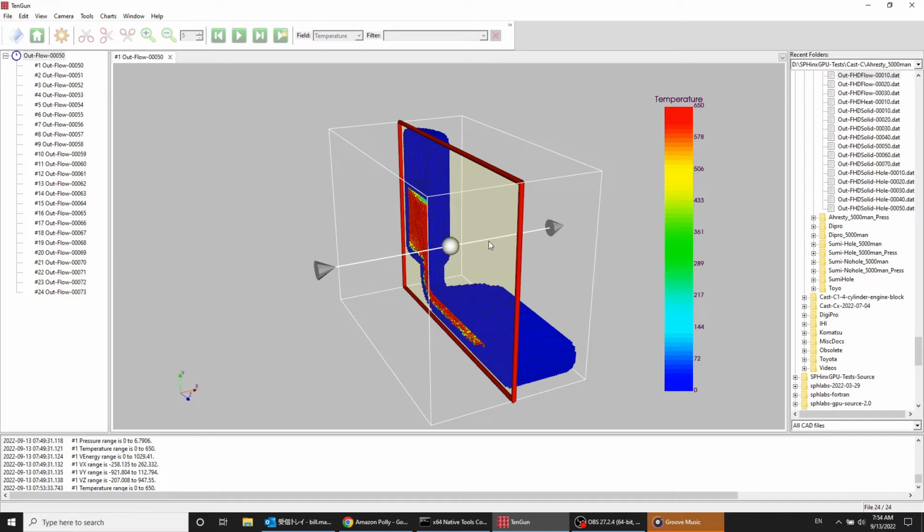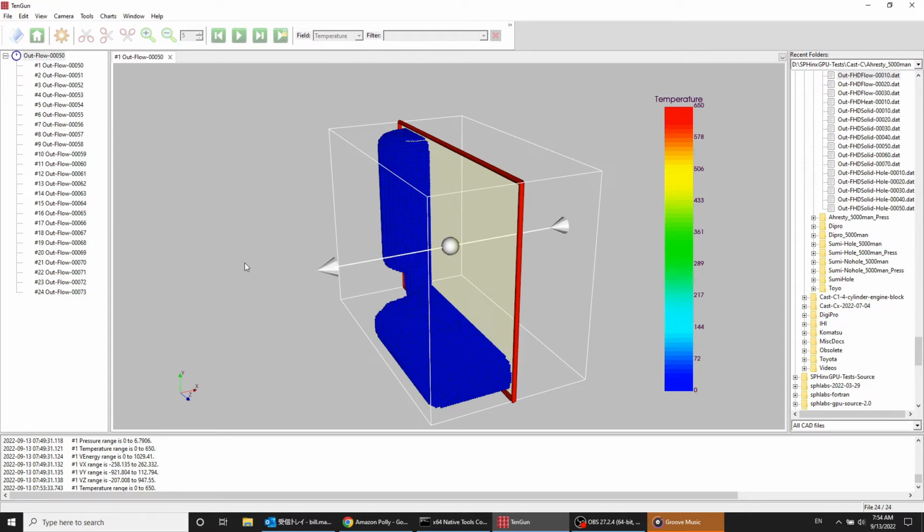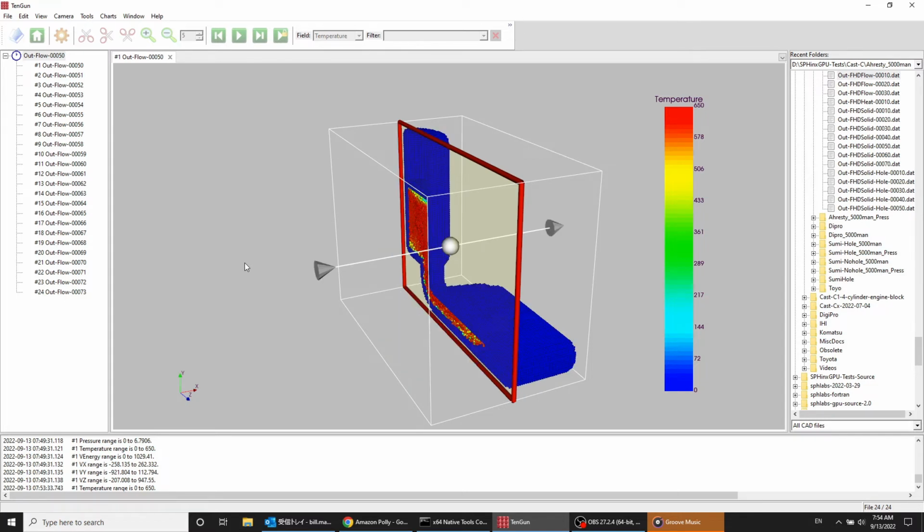If you want to preserve the other side instead, you can 1. Press I to invert the selection, or 2. Press Escape to restart the cut operation, and then press Shift while clicking one of the scissors buttons to start with the opposite orientation.